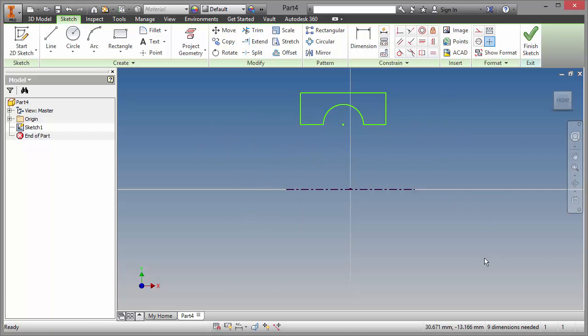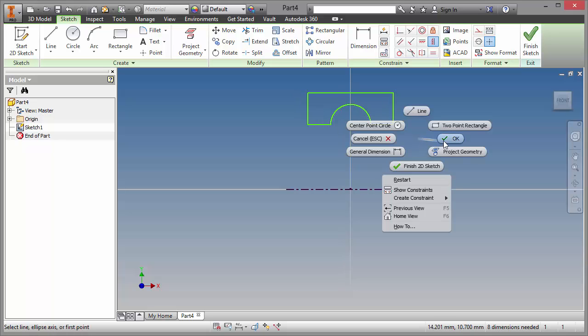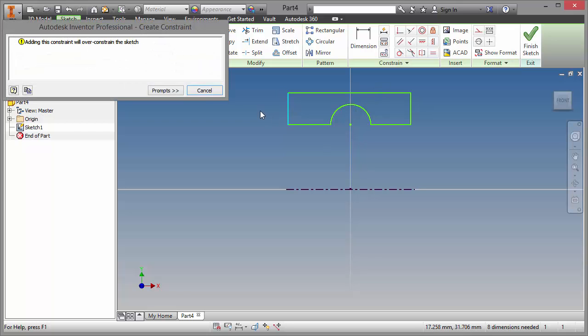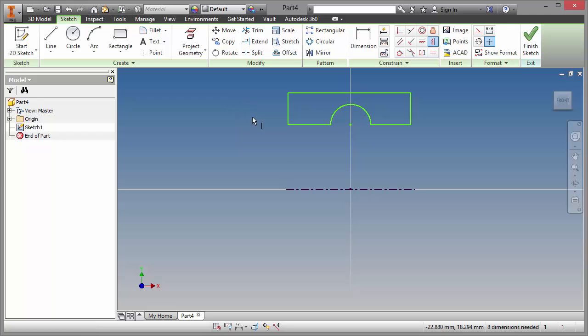and now I'm going to start placing my geometry. So I'm going to get it in the middle, and as I go I'm just checking, so it's not doing the symmetry part for the box. That's come up because I already had that line selected, so I'm just going to deselect the line, find the midpoint.